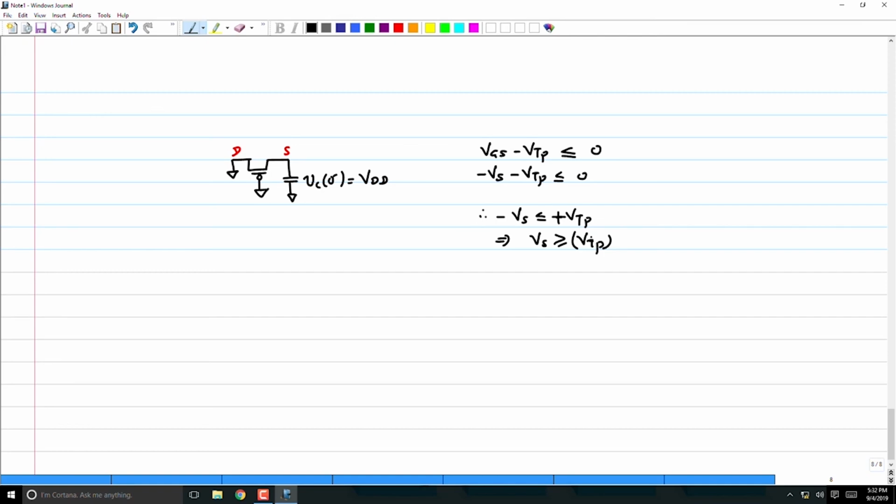Right? So how will you write this general condition? I have a gate voltage, I have some drain voltage. Capacitor is initially charged to VDD. I think this will be a little hard to put down in the general thing, because it depends on what the voltages are. So I think it's better you just apply this particular condition: identify drain and source first. VGS minus VTP should be less than 0. And then you find out up to what it can go to. Right?